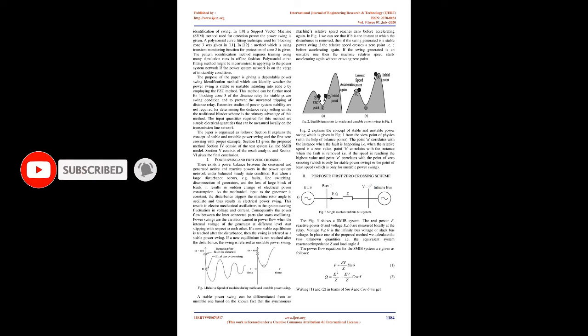The problem associated with all these methods is similar to that with the conventional blinder scheme. We need to find loci of the power swing after doing various stability studies, and all scenarios of power swing are not covered and different operating conditions are not included. In 8, a swing center voltage, SCV, technique is given, which discovers the rate of change in swing center voltage of the power system network to find out whether it is an unstable condition or a stable power swing.